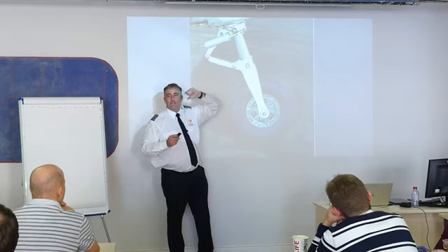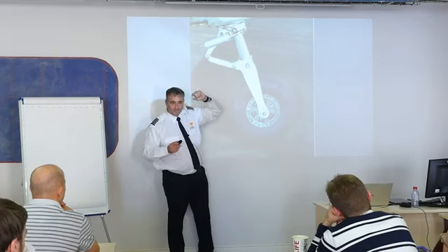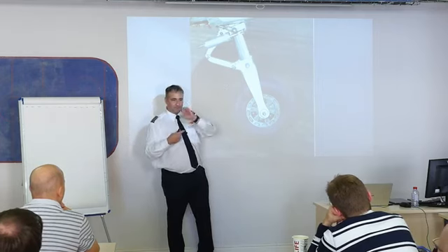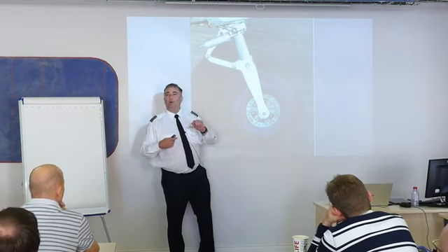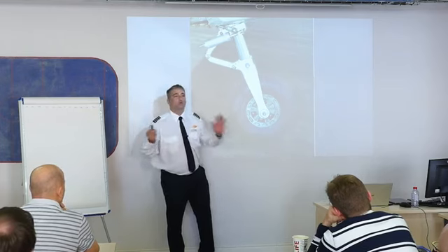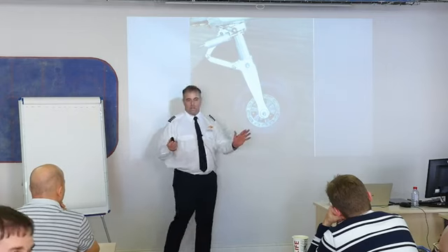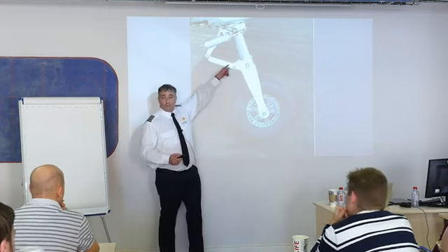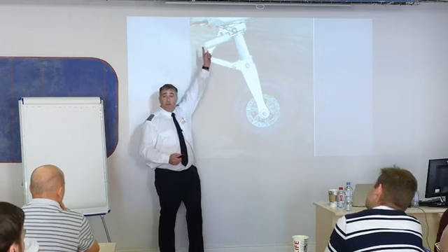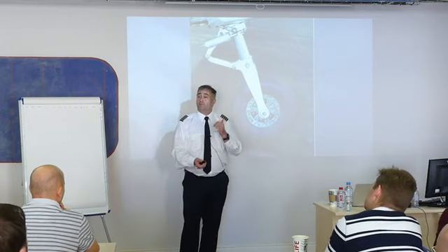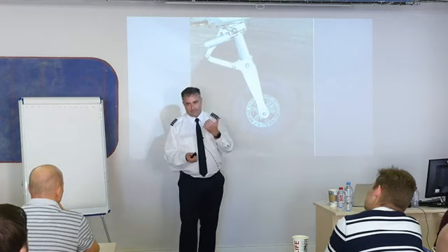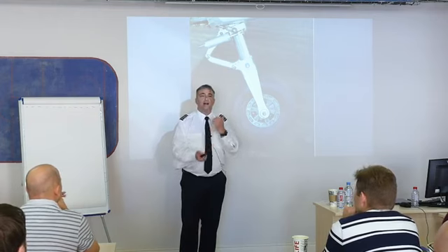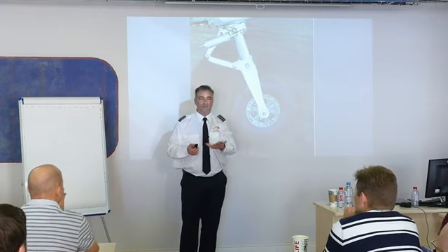Metal. Anybody like Oreo cookies? You guys know what Oreo cookies are? Oreo cookies got the black cookie and then the white center. Okay, Oleo. I don't know who in the world named this. The guy must have been named Oleo. That is an Oleo strut, okay? Meaning that this is a strut and it has a cylinder above it, and that cylinder is charged with some sort of spring or usually gas, nitrogen, okay? Has fluid and nitrogen inside there, and it allows for a nice smooth landing.